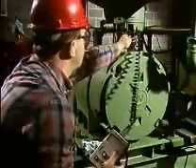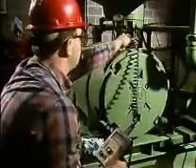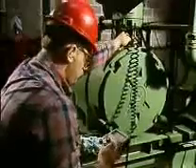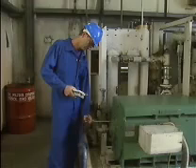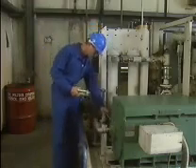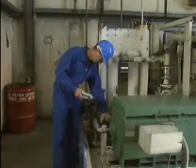Transducers can be placed on a machine in a number of ways. The method used in a particular application may depend on the type of machine that is being checked. If a machine that is being checked for vibration has more than one set of bearings, each bearing should be checked if possible.